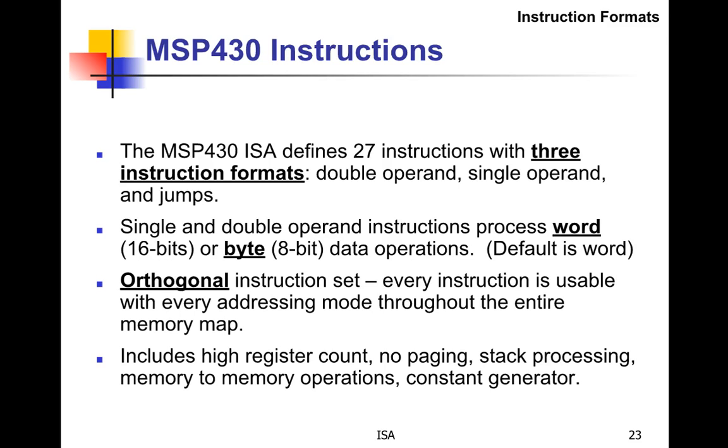MSP430 has an orthogonal instruction set, meaning that every instruction is usable with every addressing mode throughout the entire memory map. So you'll understand what the addressing modes are in a little bit. It includes a high register count, no paging, stack processing, memory-to-memory operations, and constant generator.